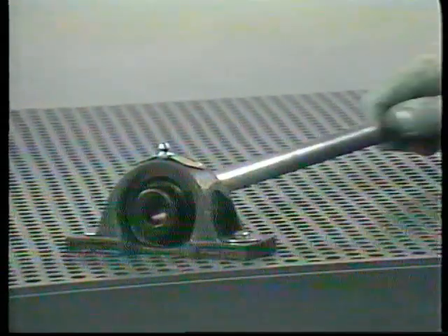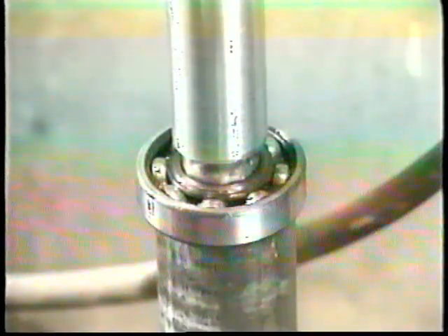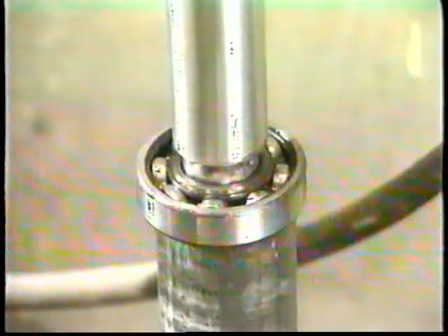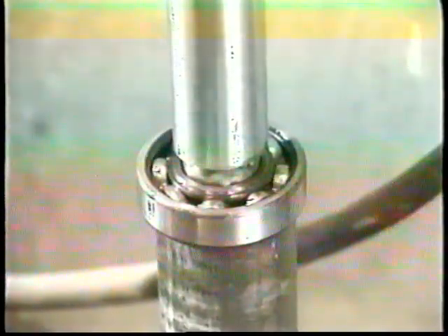The fit should be firm, or a push fit, as it is called. This allows the bearing to be installed or removed by hand, but just barely. There should be no detectable slackness. Manufacturers have devised a system of tolerances for both shafts and bores in order to ensure the correct bearing fit. Reference should be made to these charts when new bearings need to be installed. When the load and a bearing ring move together, the fit must be considerably tighter, or the ring will creep around on the shaft or in the bore.